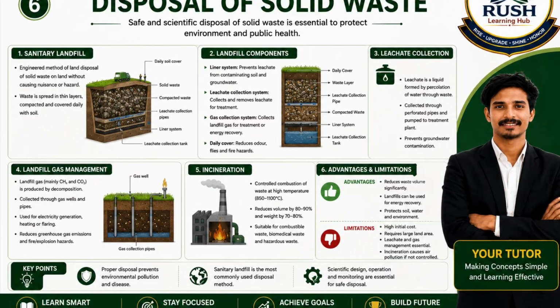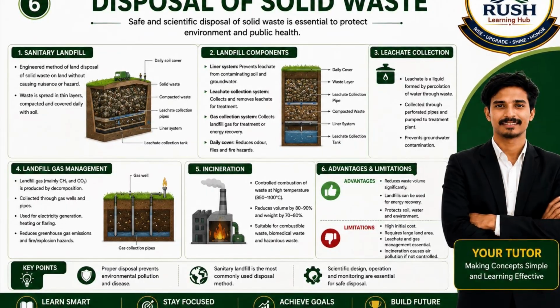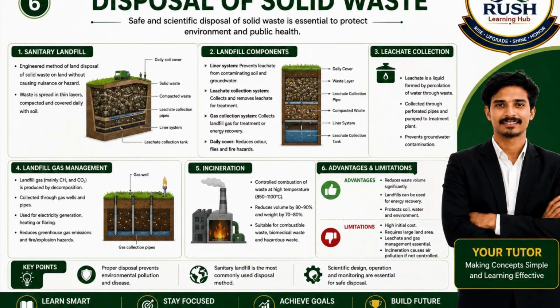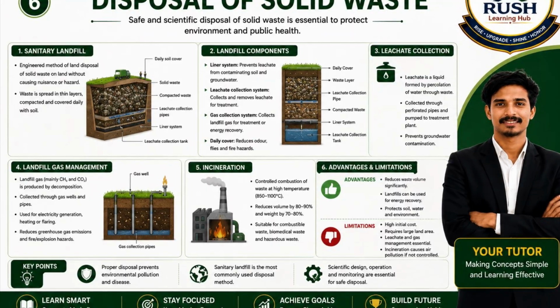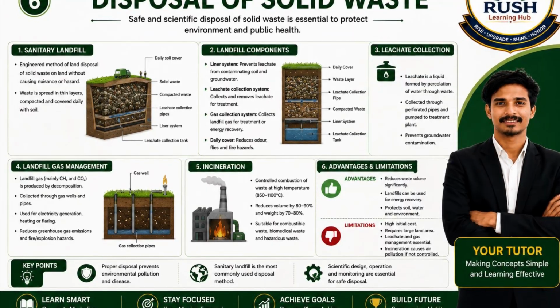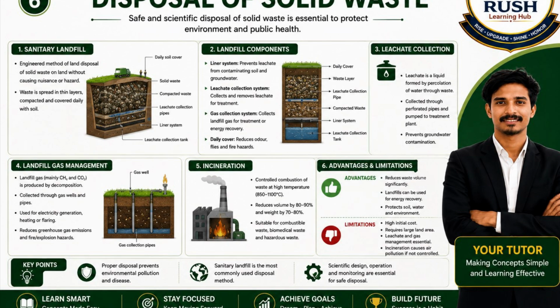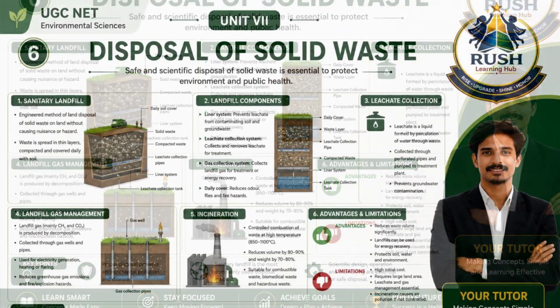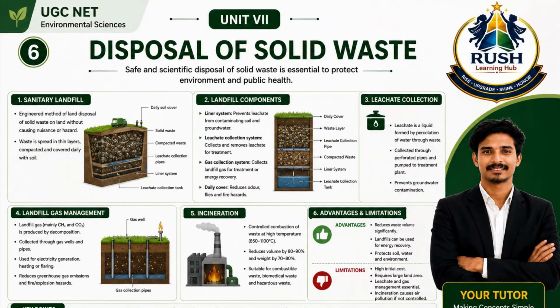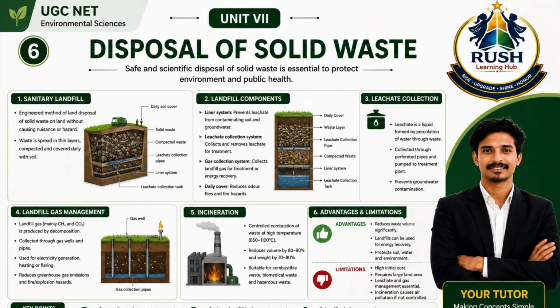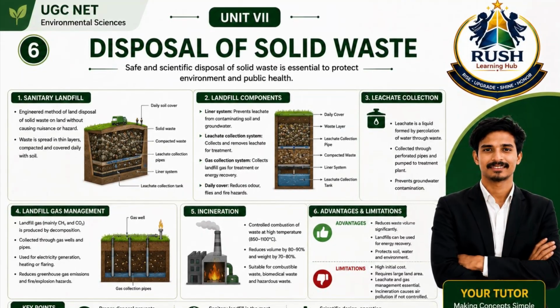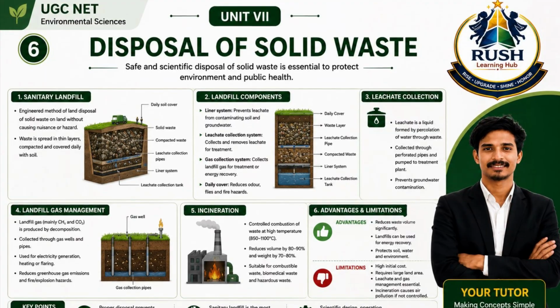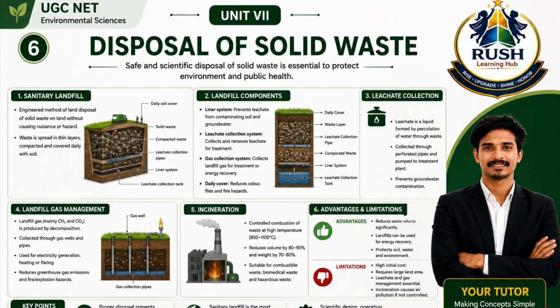When the landfill reaches its maximum capacity, it is sealed using a final cover system. This cover consists of compacted clay, geomembranes, drainage layers, topsoil, and vegetation. The final cover prevents rainwater infiltration and minimizes environmental pollution after landfill closure. Now let us understand landfill management.